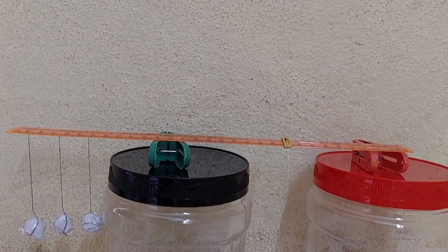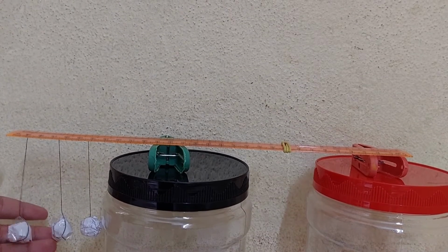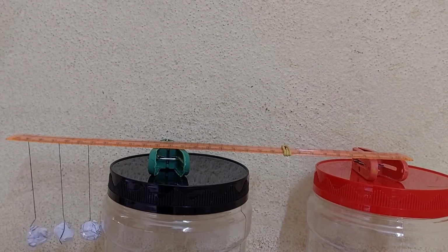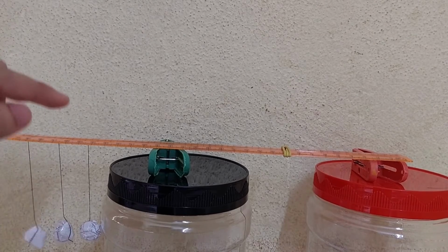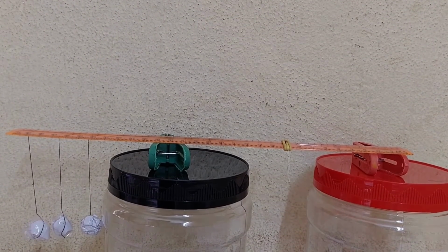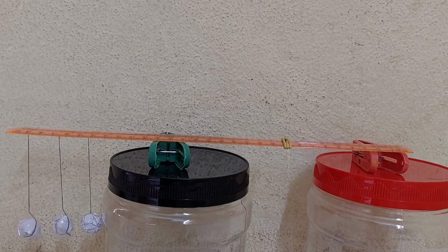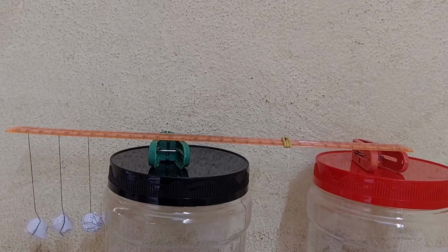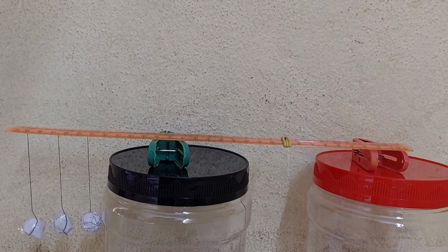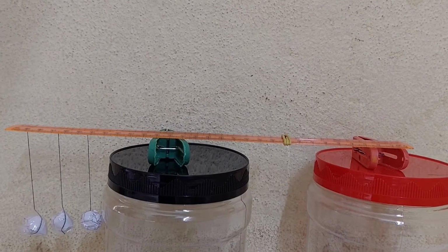Second step, three series of point load are placed 40 mm apart from one another at the left of the support B. Then find the shear force that the digital display will show you at the section XX. Done for this experiment.